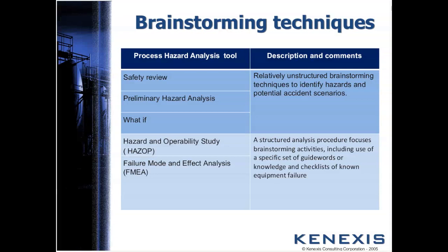operating procedures. So it formulates a list of hazards and generic hazardous situations by considering things such as the facility layout, plant equipment, raw materials, the operating environment, operational activities, testing, maintenance, things like that.